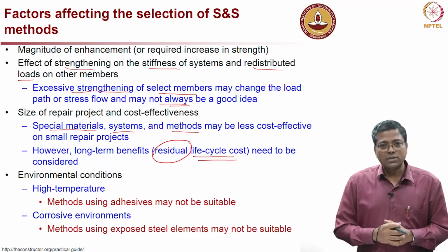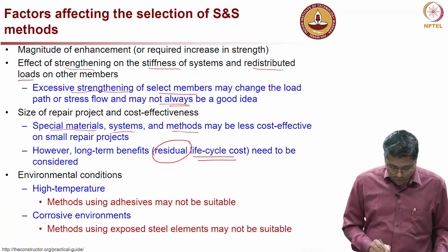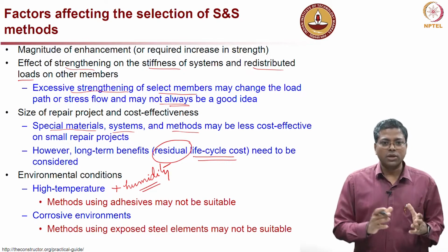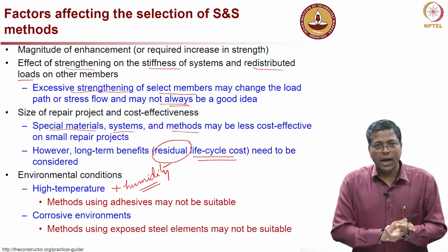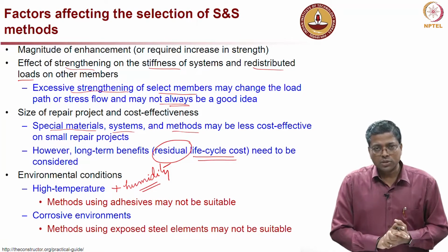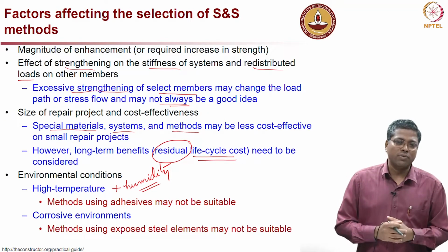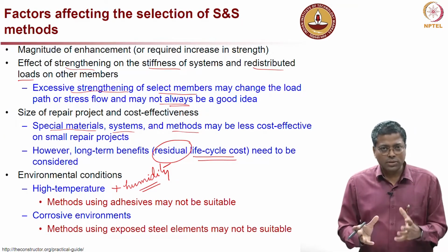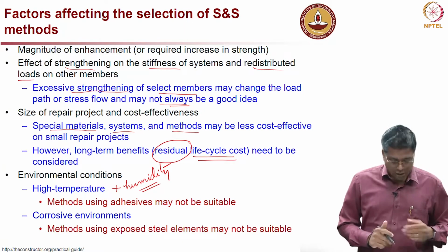Now, environmental conditions are also very important to consider. For example, high temperature and humidity. If you are talking about an adhesive which is used for a repair procedure, that adhesive should work even at high temperature, or whatever temperature condition is prevailing, and whatever moisture condition is prevailing, it should work in that condition. So, the selection of materials should definitely depend on the environmental conditions.